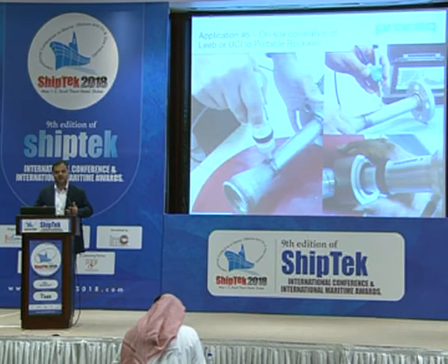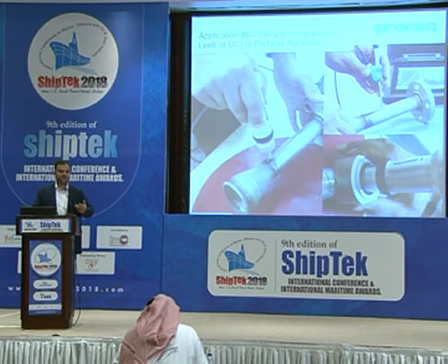Whereas for higher thickness, large components and heavy samples, in that case, LEEB is the most established technique. And the UCI is very good for precise positioning on the welds and the heat affected zones, especially for weld and HAZ testing, UCI is the most established technique. So based on the application, we can use different techniques, and in some cases, we can also combine different methods in order to achieve the most reliable data.